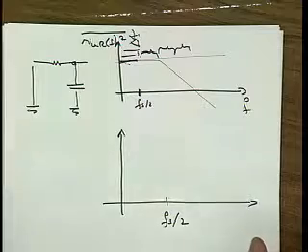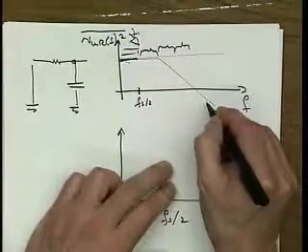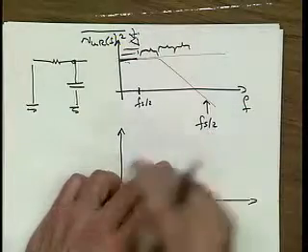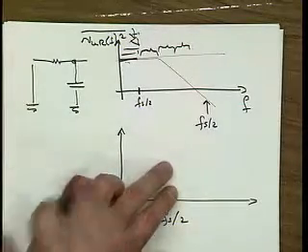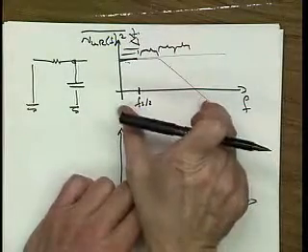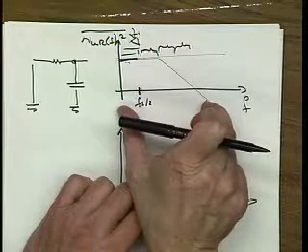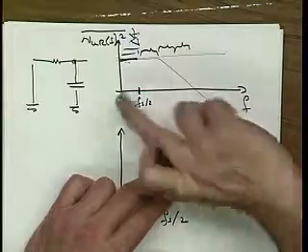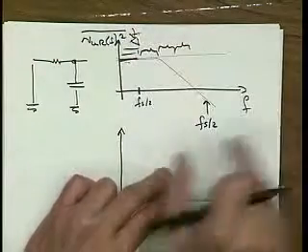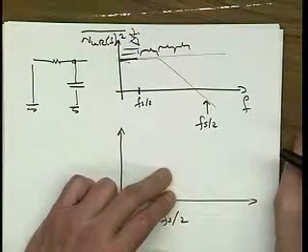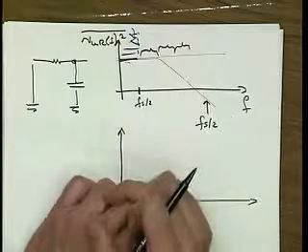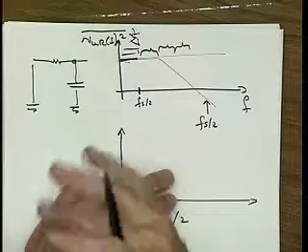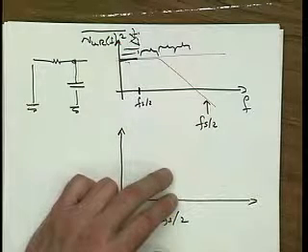Okay. Another extreme would be, let's say we sample with this frequency, make this fs/2 now in our second sort of thought experiment. Now, this thing stays put. Right? Then the next sliver here with the triangle gets flipped around and is added here. And then another triangle that doesn't get flipped around is added here. What do you think the end result is going to be? Sort of roughly, the spectrum of the end result.